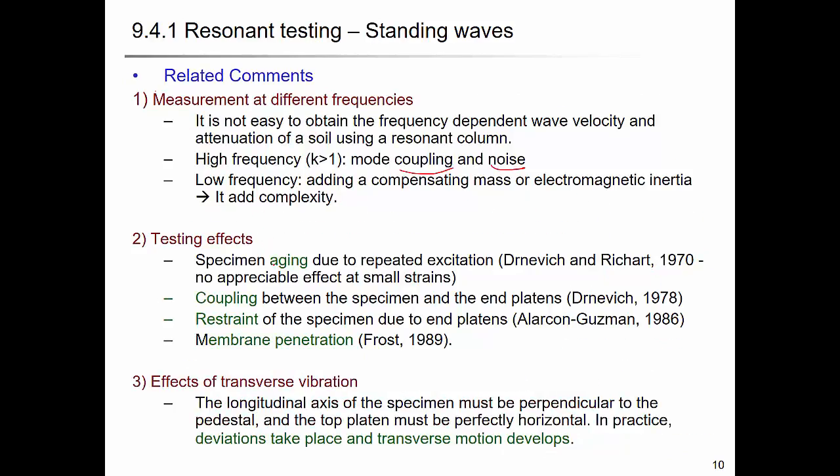And testing effect, specimen aging due to repeated excitation, in particular when you apply the high strain. It's like a strain hardening behavior. As you excite more, the soil gets more compacted. If you start from the loose state, in the end, after the experiment, the density will have changed. The density will become higher because it gets more compacted. It's like you are applying vibration to compact the soil.